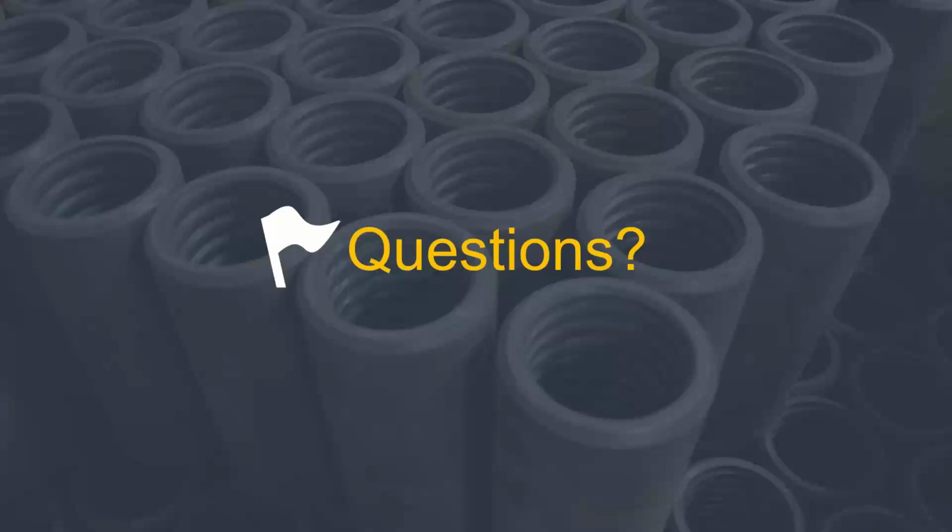It's just definitely not the most optimal for really controlling those foundations, and you're allowing it to rotate around your pile more than you'd like when you don't have that bracing. Not to say it can't be done, but you're basically assuming some risk to the superstructure whenever you allow that pile head or that pile cap to move around, translate, and rotate when you don't have multiple piles fixing it in place. So it's not right now, but go ahead.